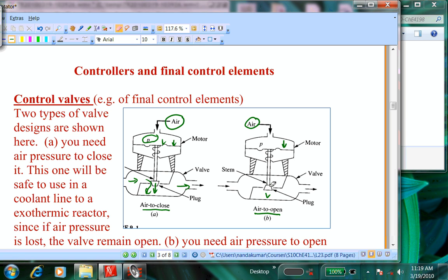I would simply, I don't have all these complicated designs. All I need to have is something like this, a flat one. So it just shuts off, or when it opens, it opens. So I don't need this tapered design there. Okay? So that will make it cheaper to manufacture for the valve. So when you are selecting your controller, you need to select the valve that goes with the controller and see which one meets your purpose.